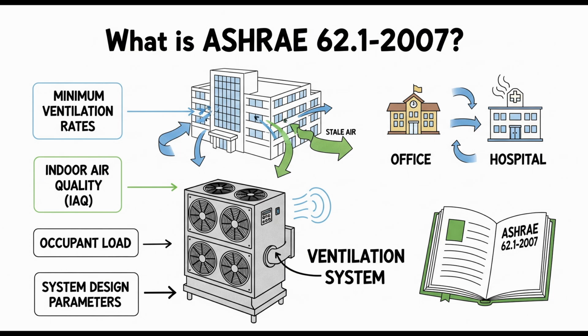Class 2 air has moderate contaminants, maybe mild irritation or mildly offensive odors. Or it's just air that's not suitable to mix back into Class 1 spaces if they serve different purposes, maybe a beauty salon, certain lab areas, some retail spots. Right. Class 3 air has significant contaminants or offensive odors. Think air exhausted from commercial kitchen hoods or maybe a trash room. Okay, so you're basically grading the air based on how dirty or smelly it is, and these classes determine where that air can go next.